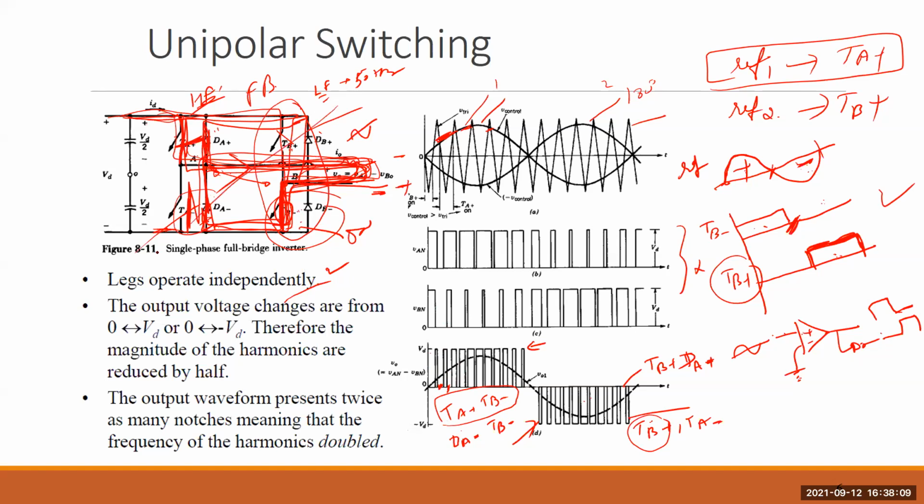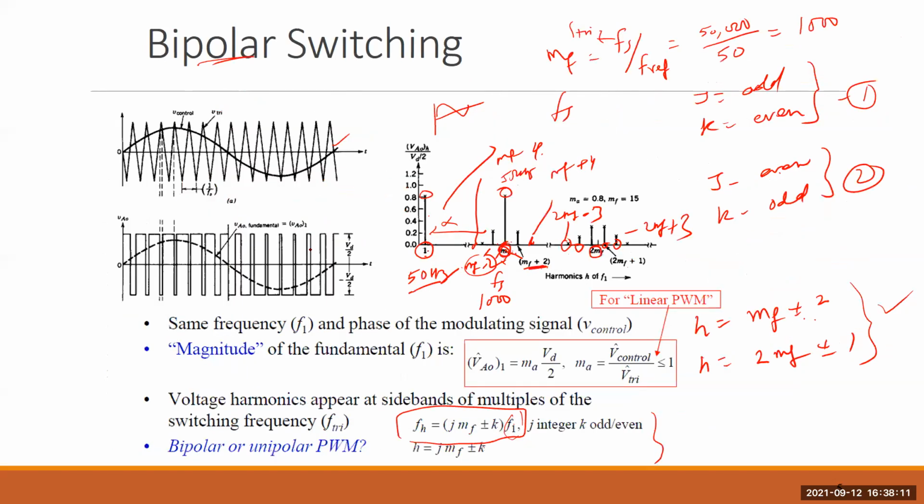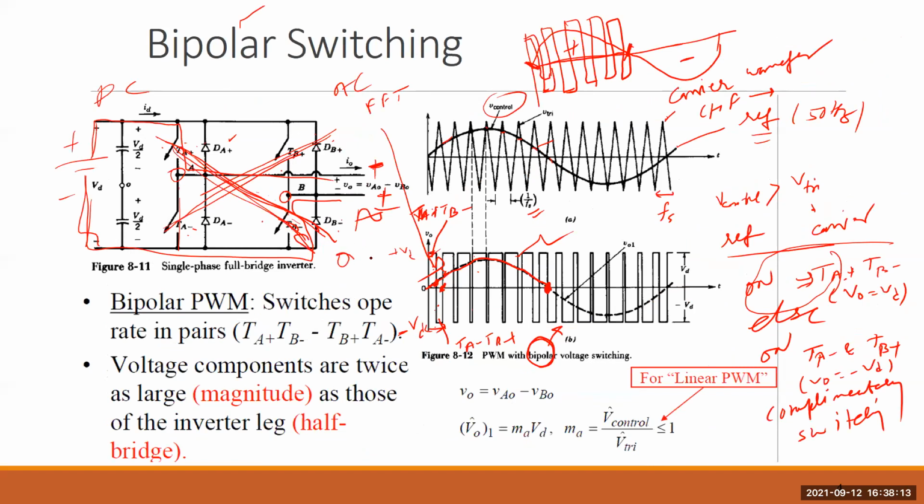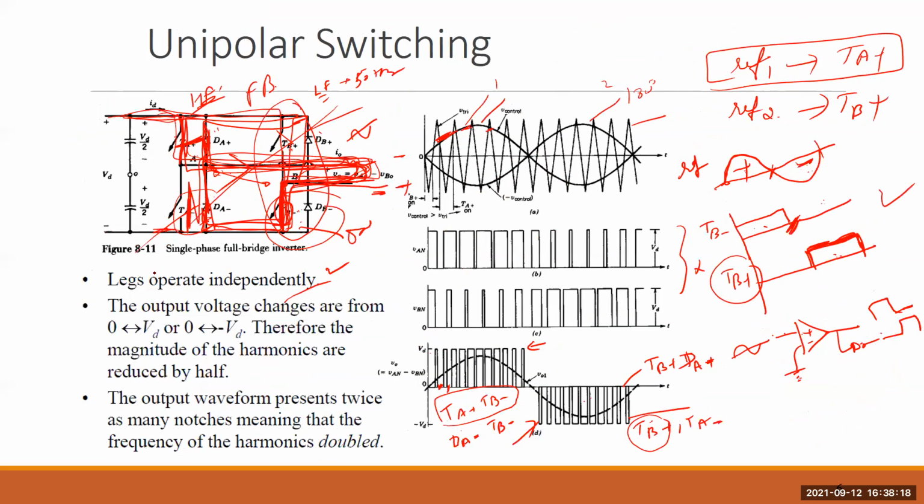Earlier you immediately change the switching, right? Earlier either this is on and you turn this switch off immediately and you turn this pair on. Right now we are not doing it, we are doing this pair continuously on, so that this current still flows and then finds the alternative path, causing a short circuit, causing a zero voltage instead of going negative.